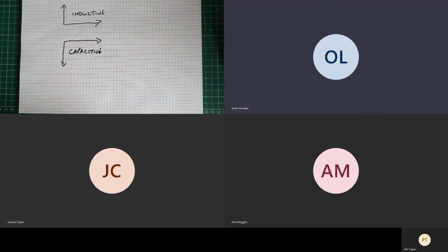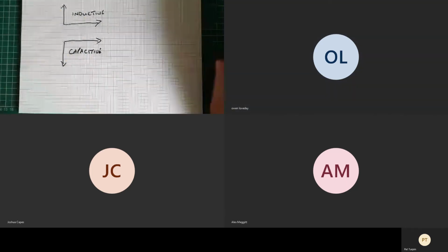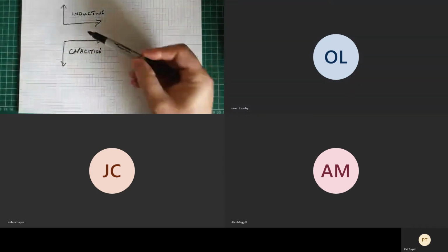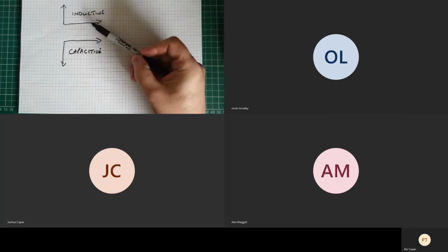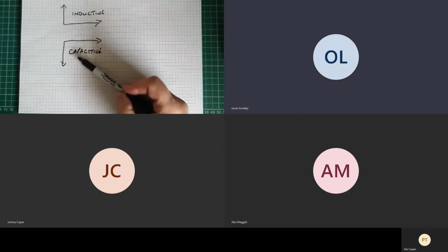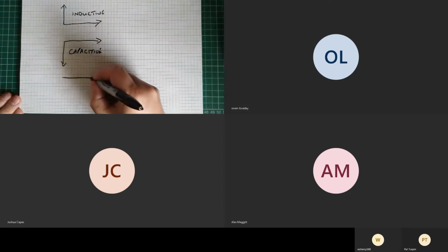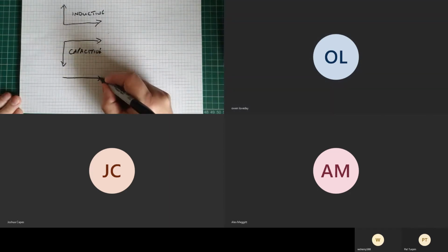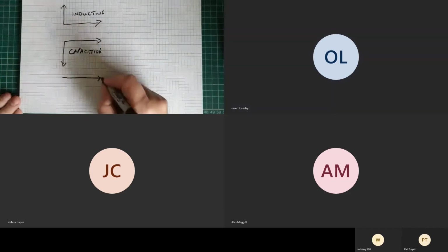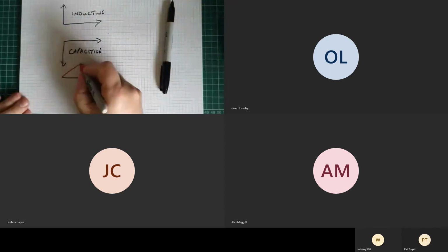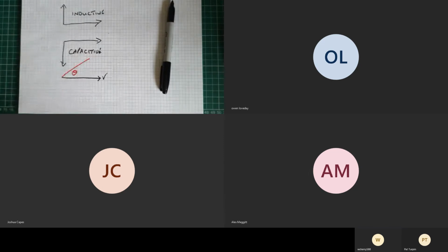Most loads that involve electrical windings, such as motors and transformers, would actually have an inductive element. So we use a capacitor to offset one against the other. So if you were asked to display this in polar form, you would draw the voltage and then the current, stating the relative angle.